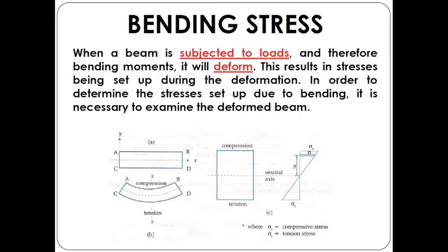Right, so this can also be determined when we determine the bending moment diagram. With the bending moment diagram, when we have a positive bending moment, as I have already explained earlier, if we are considering that the positive bending moment is at the bottom of the beam, therefore it is under tension at the bottom and under compression on top, right?